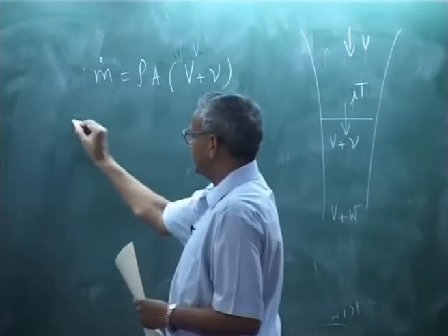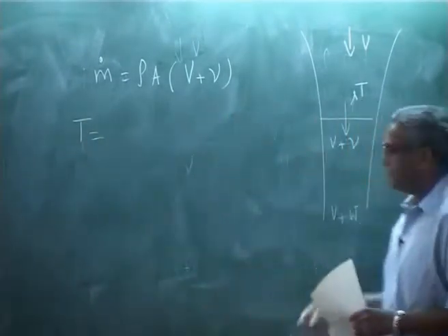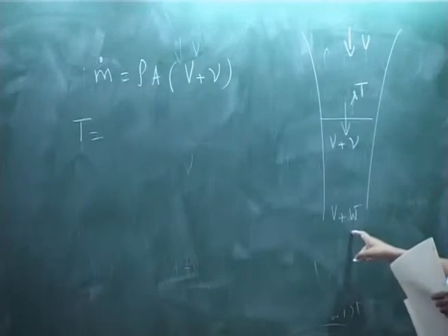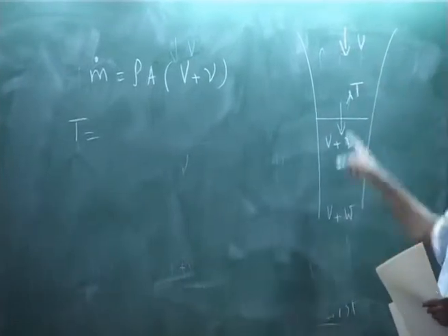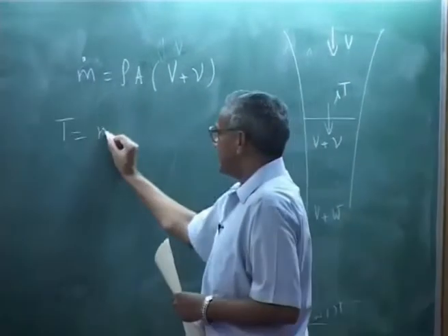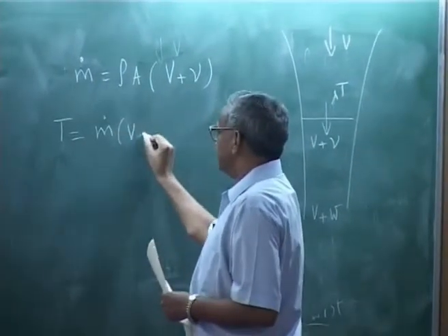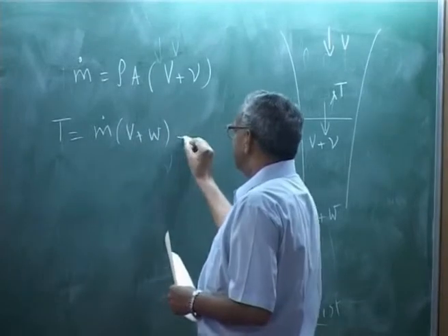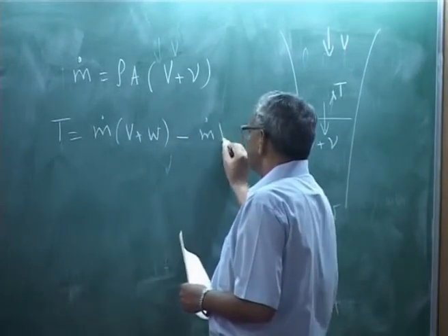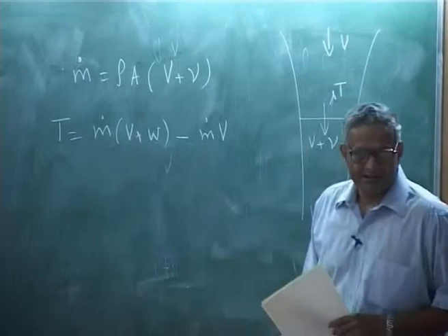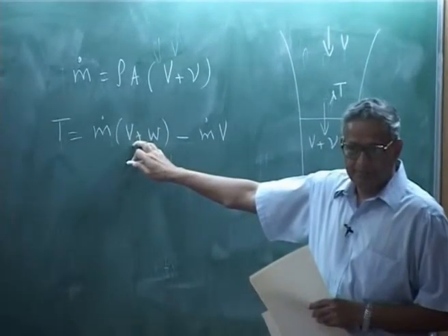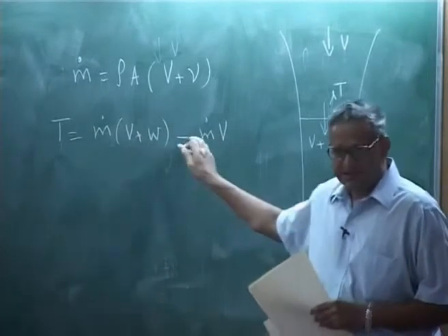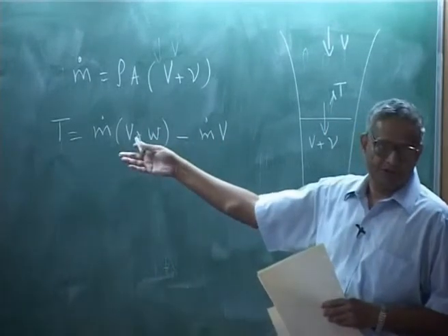Thrust is the change in momentum from initial to final, or final minus initial, that is m dot (V plus W) minus m dot V. Because these are rates, that is nothing but the force.